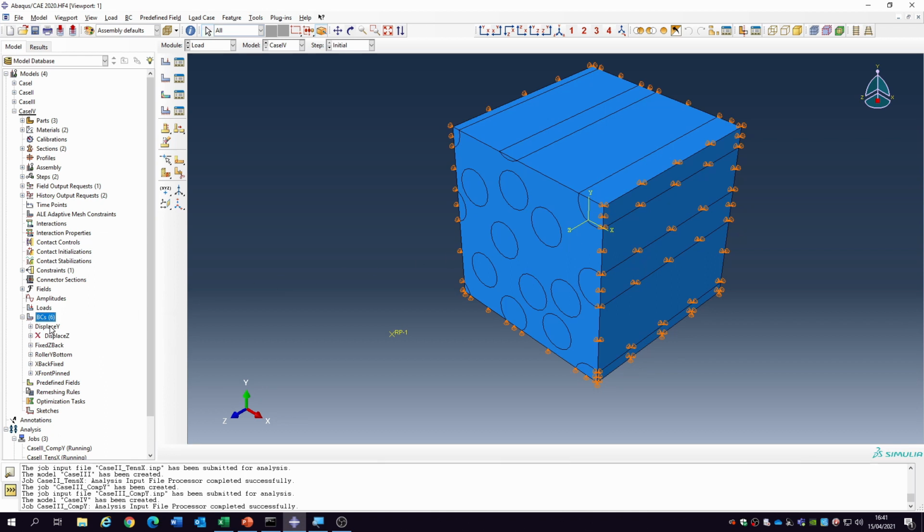And then obviously our displacement load will be linked to that face as well. And how are we going to do that? Clearly we need to cancel out this particular one at the bottom, X, Z, Y bottom. So I'm going to suppress that, so it's not free to do anything in that face. The back one also needs to go, which will be fixed back. I'm going to suppress that. So thinking about the boundary condition we've used, we fixed at the back and we are rolling at the front, keeping the system the way it's going.